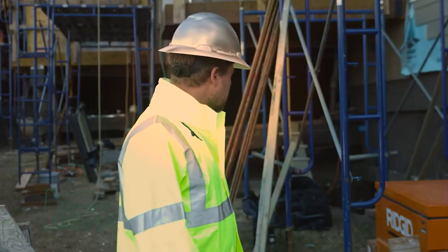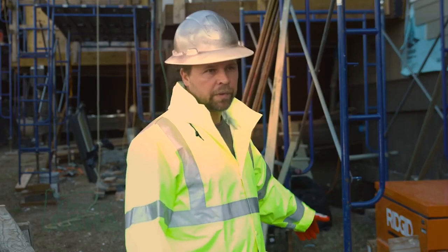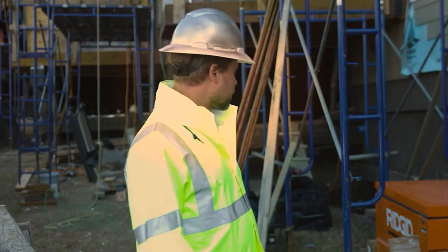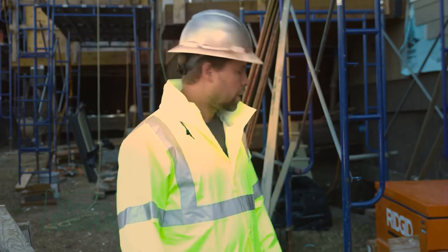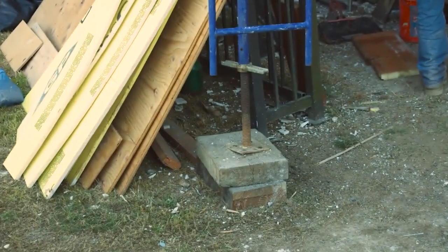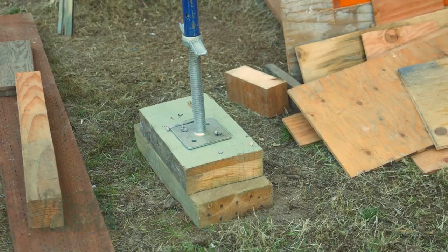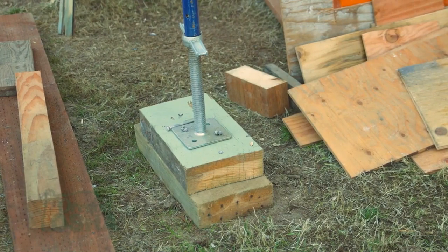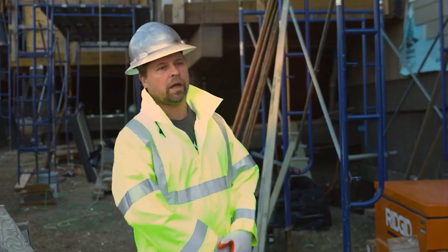Well, obviously it starts from the ground up, so I want to make sure that the surface is properly prepared. There are some uneven surfaces, so I want to level it out, or do some digging to stabilize it. We want a solid base because we don't want something to be depressed in the ground later on, since the rainy season is coming. So what we have now might be different later on. So I want to have a pretty wide base underneath the scaffolding.